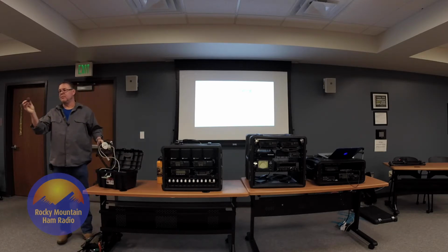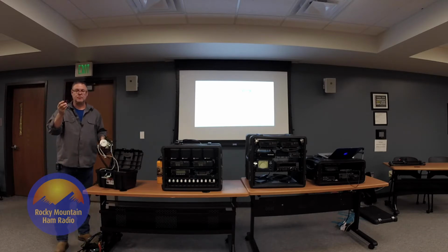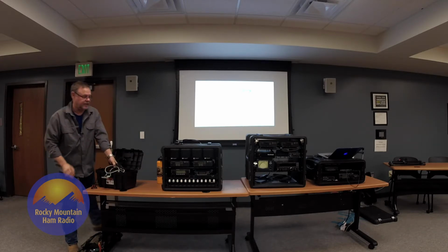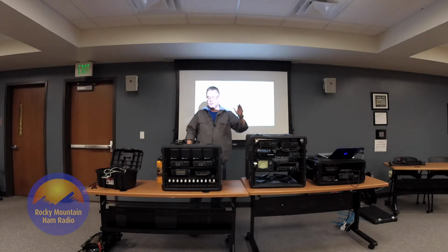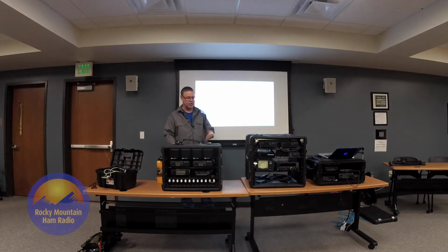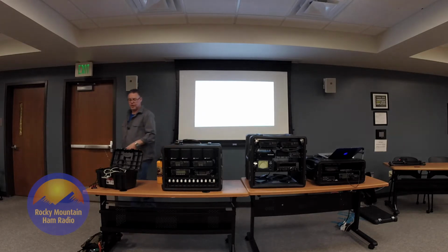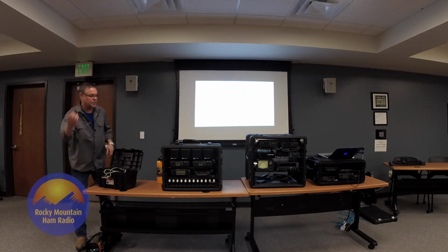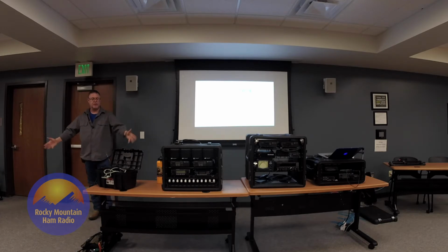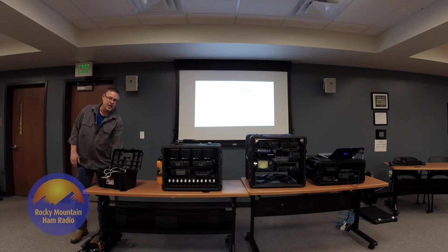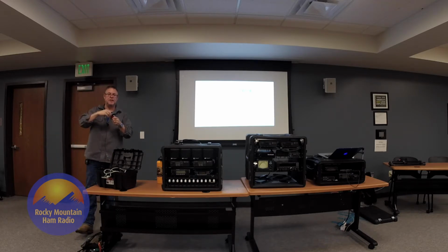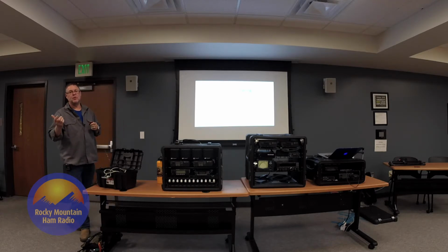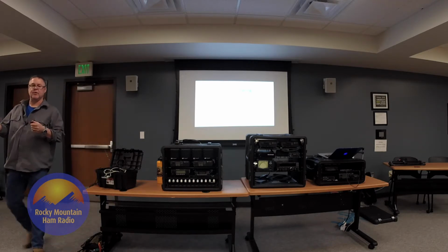Always carry an extra 1 or 2 power pole adapters so you can spread out power. Once again, this one carries not only 110 volts that I can share with John's rig or whoever else needs power, or an extension cord or a computer or whatever the case may be, but I can port out 12 volts also, up to 30 amps. So having this available so you can set it right here and plug in 2 or 3 other 12 volt items is handy. Having pre-built cables that have power poles on them that plug into this and go into 5 volt USB adapters or transformers, converters, whatever you want to call them.